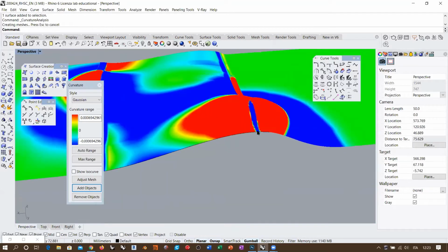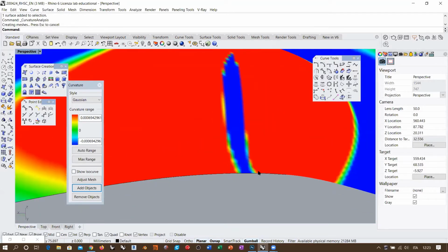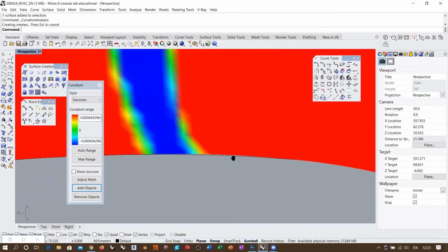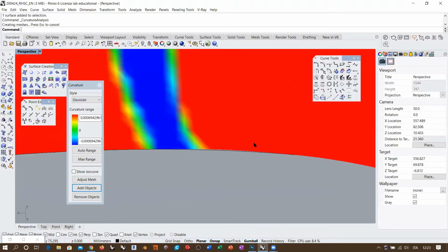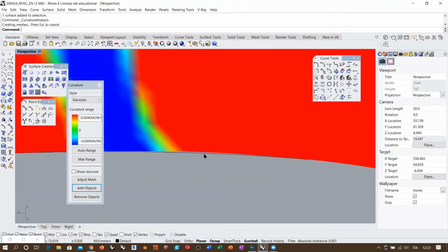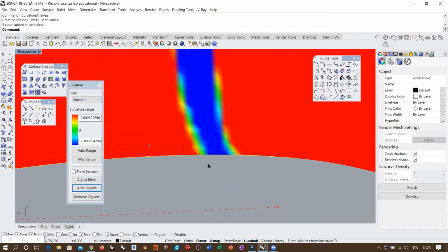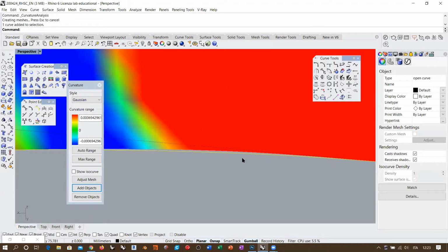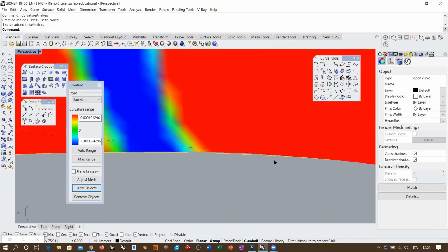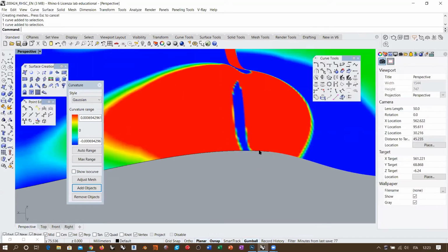Moreover, you start to have some problems in this connection part, especially because you can see that the surface is continuous, but you are not respecting the curve, which was this one. Because the first three control points of the 32 control points curve that you have rebuilt inside the command are being displaced in order to have curvature continuity. So the displaced or rebuilt cross section does not correspond to the cross section that you were using, okay?